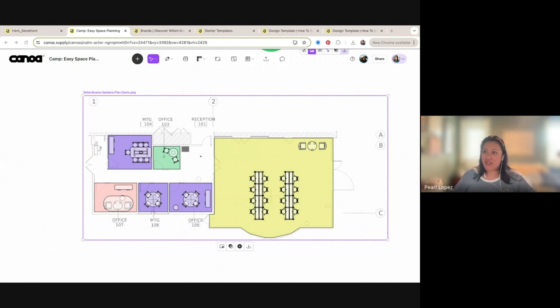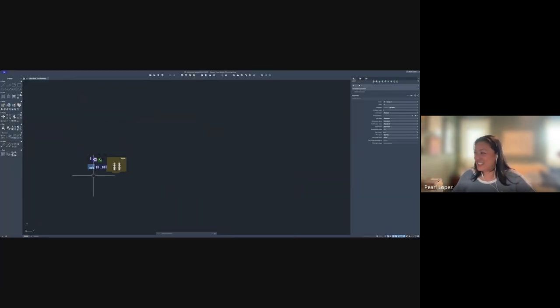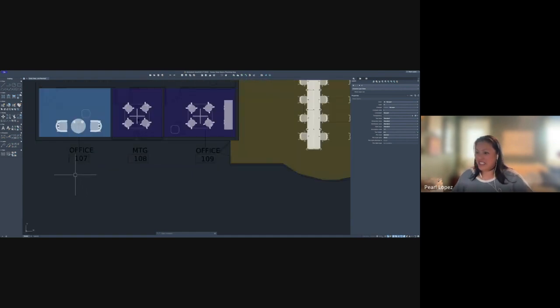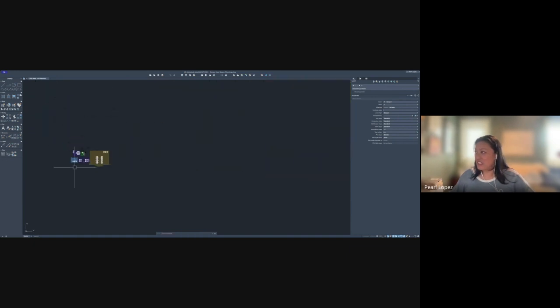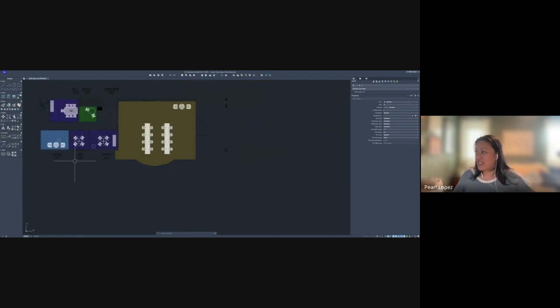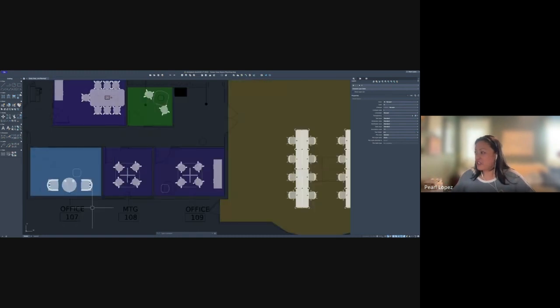Let me switch windows real quick so that you can see my CAD. One second. So this is that file that I opened up now in CAD. And so very faintly, you can see this is the base plan. It's been XREF'd in there, which I can turn on or off. So if I had the actual CAD of this, I can lay this right on top. I can turn my image file on so I can use that as my point of reference so I can line up my drawing, and then I can turn it off when I don't need it.